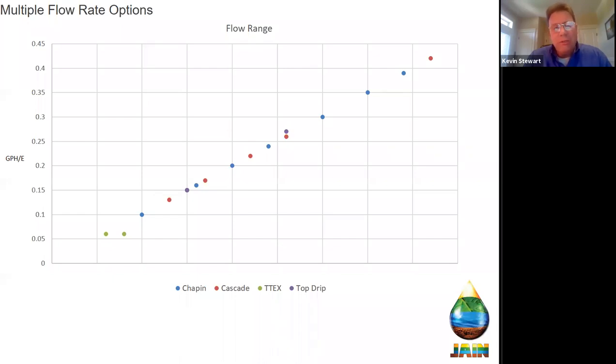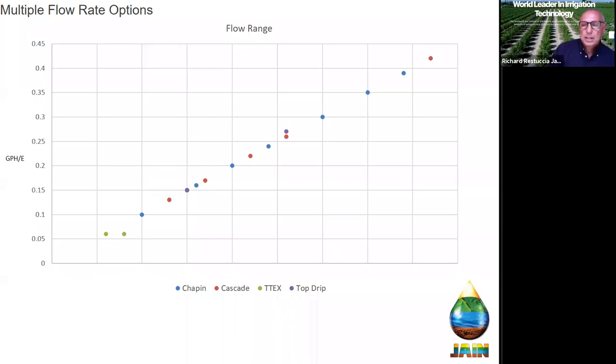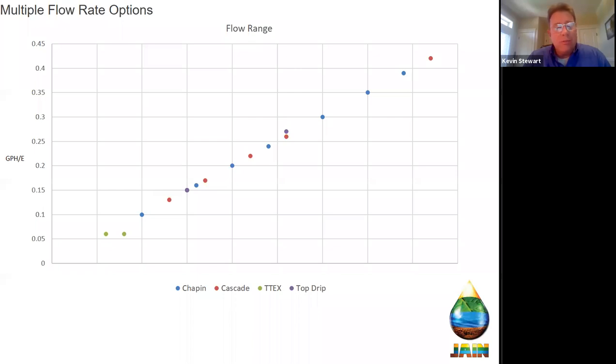I don't think you would use really drip tape for that. You'd want to use something with a heavier, a bigger wall, probably a 45 wall. And so we're talking 20 mil is where we max out at drip tape, and you probably want to be double that on a commercial landscape or even on just a landscape. But yeah, I think it's probably done more often than not.